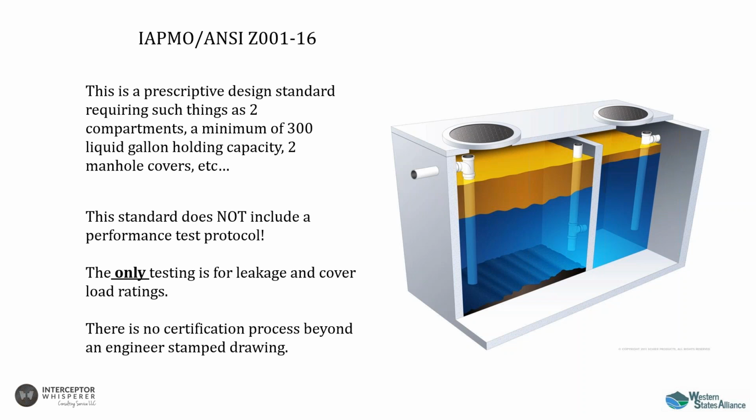If I opened up that standard and walked you through the whole thing, you would simply see prescriptive design elements. And when you walk down to what we're testing it for, well, structural load testing is required, cover load testing is required, and a leakage test is required that assures an owner that when you install this box in the ground it won't leak. But that's the only test. There's no performance test in it.